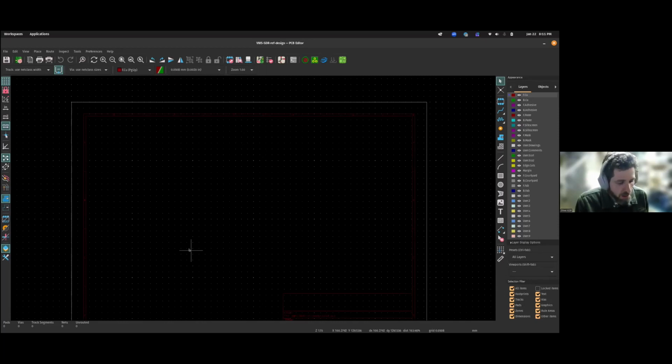The first thing you want to answer for your board is how many layers of your printed circuit board you are going to use. The very simplest circuit board is a one-sided board where you just use a copper plane on the top of the board and you ignore the bottom. No one does that. The next simplest is a two-layer board. Imagine you've got copper on the top, dielectric in the middle, copper on the bottom. So you can draw traces or place components on either side of the PCB. That's the simplest thing to do, and it's the cheapest kind of board to have made.